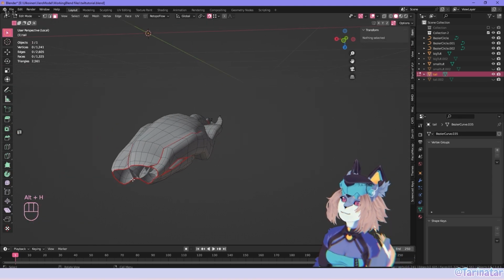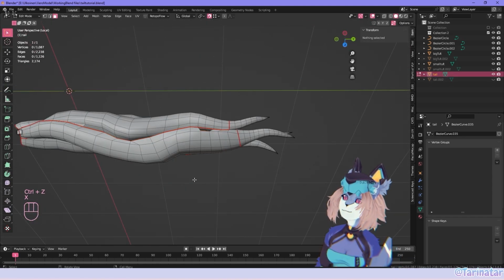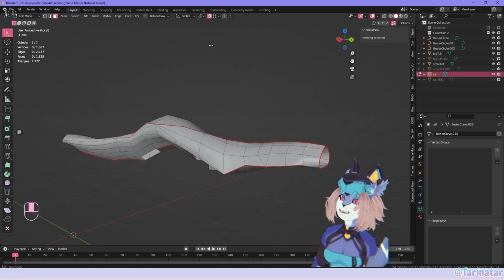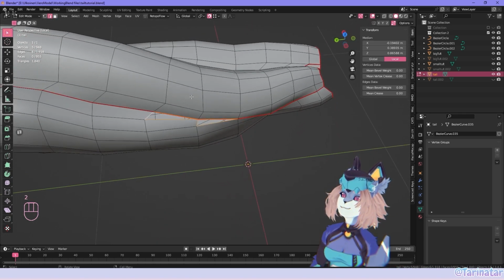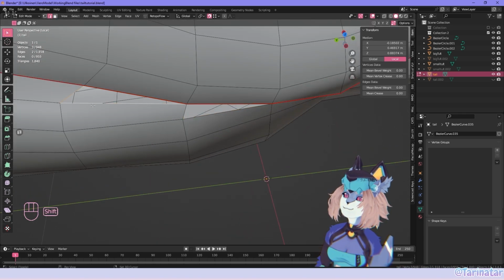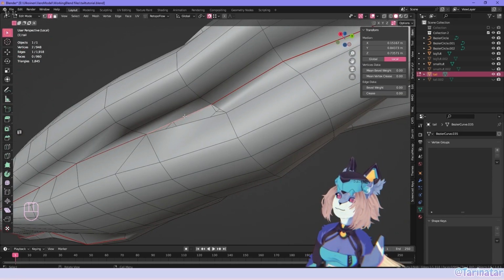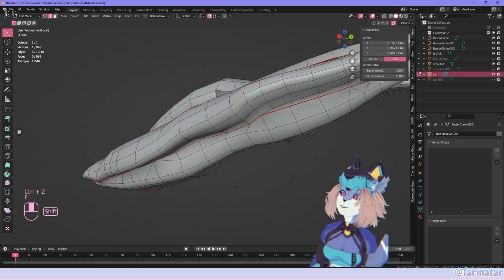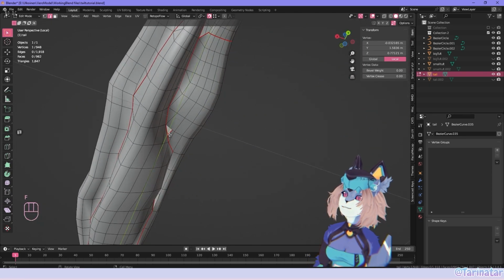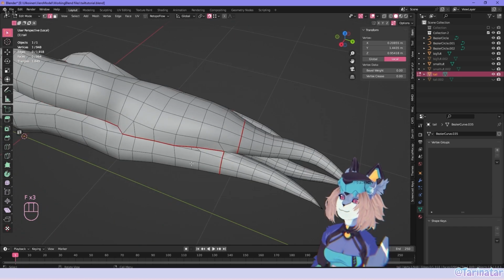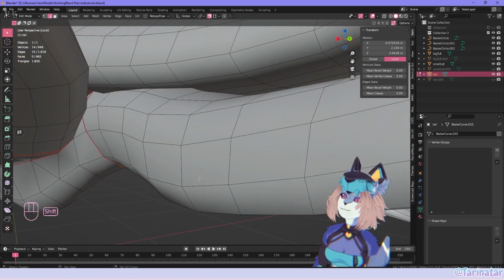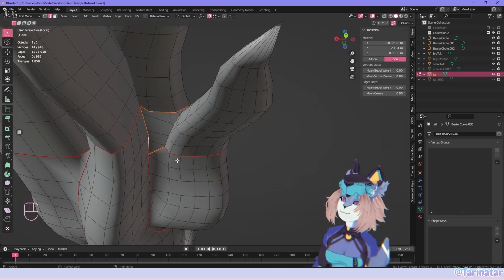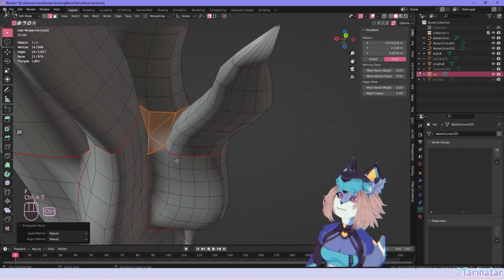Now we should be able to link select the internal parts. Delete the faces from that. Now we can easily get all these just filled. When you fill, which side your cursor is on affects the fill. So in general, it's good to have the cursor on the direction where you want to fill in. And if you have a huge hole like this, you can fill it with F, and with Ctrl T, triangulate it.